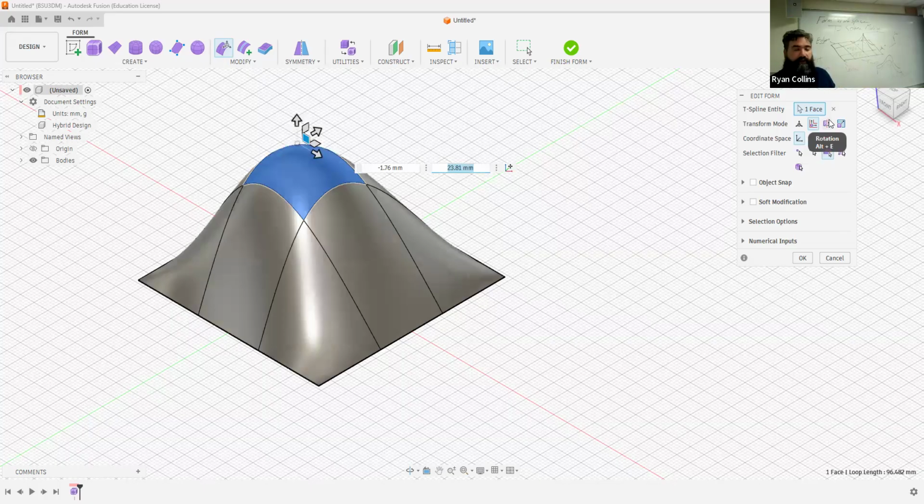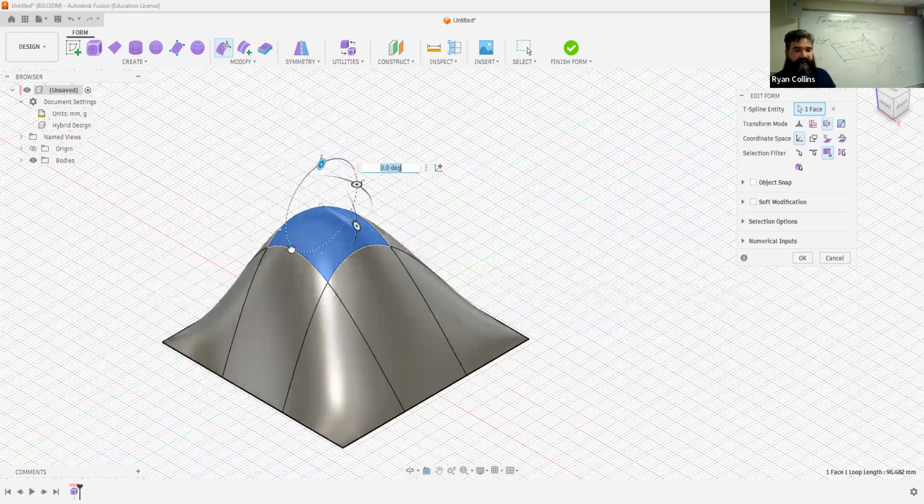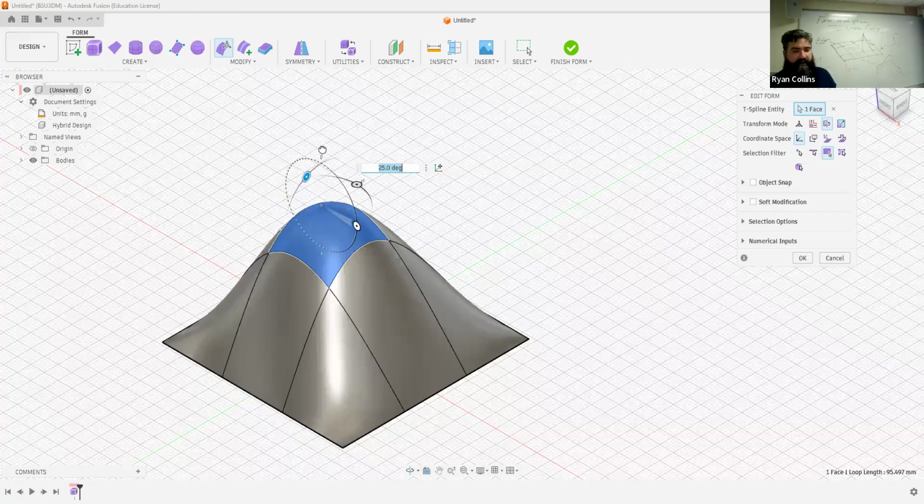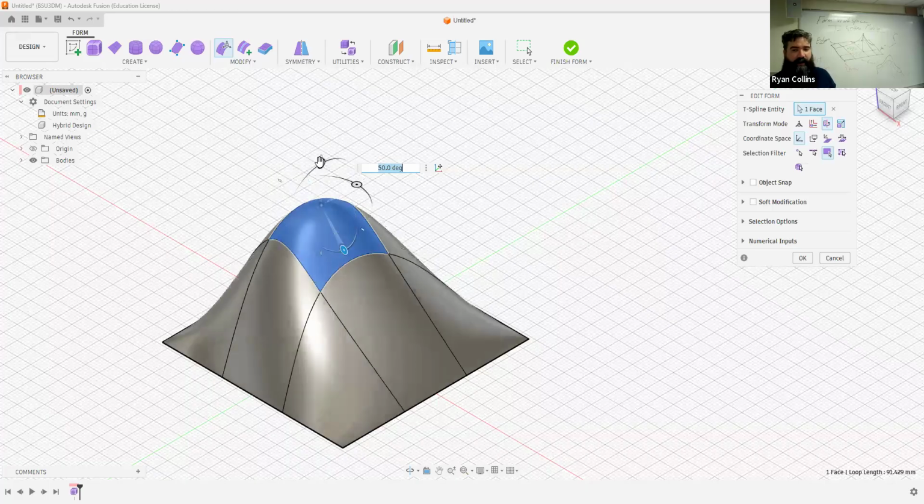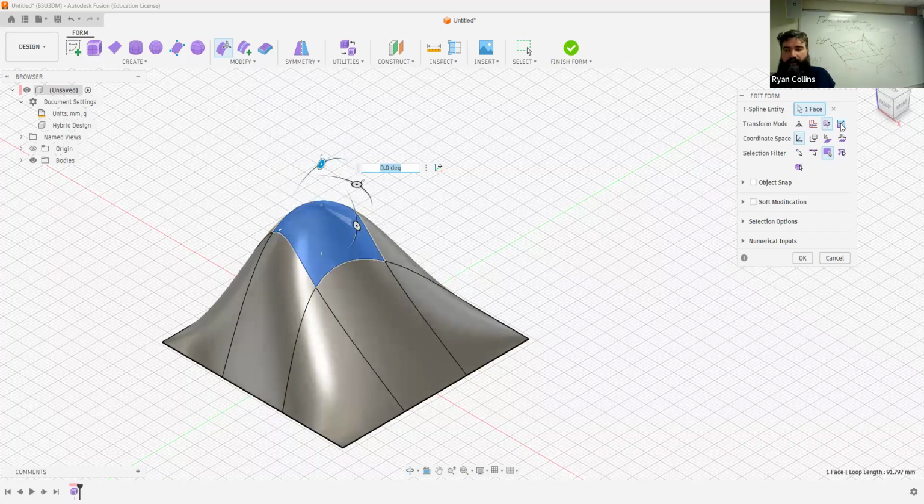Now I go over to rotation. This can allow you to exactly rotate. Of course, you do not want this to self-intersect, but that can happen. Rotate allows you to select any dimension: around the X, around the Y, around the Z. The last one is scale. And you can see these little lines. They're straight out, and then there's the little curved corner, like a little tiny fillet floating.